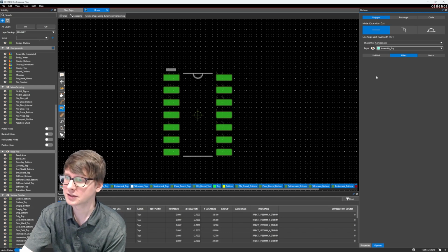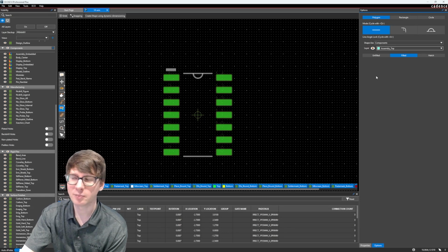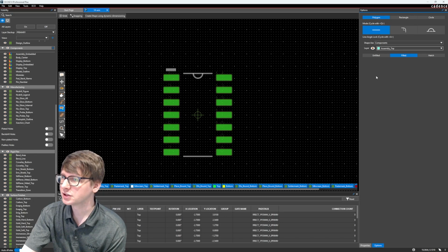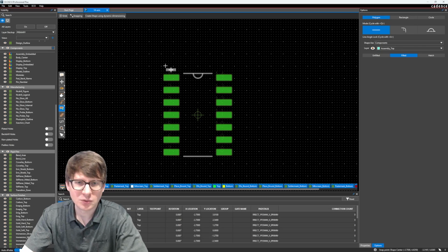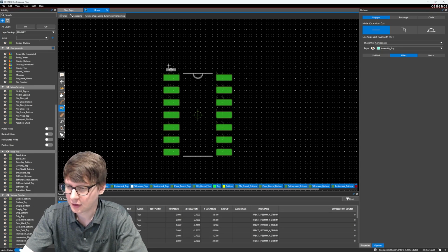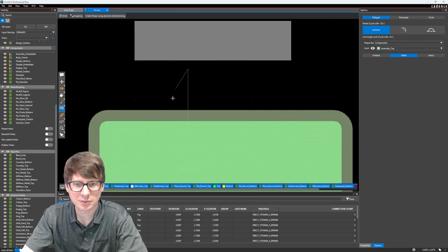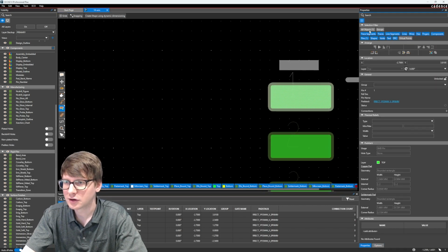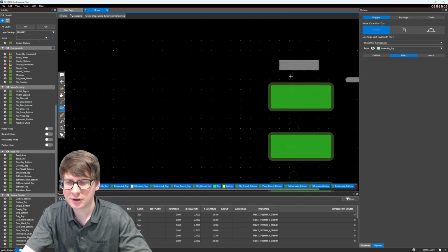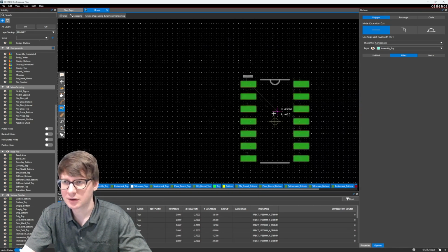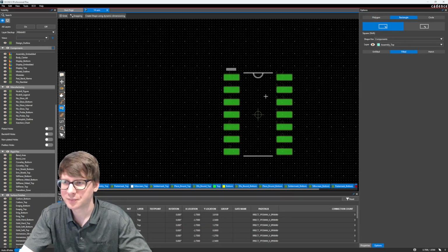For assembly, I like to use the entire outline of a component, including its pins. So looking at the data sheet, it should be 6 millimeters wide by, again, let's use that 8.6. So we'll go out to 3 millimeters in the X direction, which is right here, and should stick to our 4.3 on the height. And let's go ahead and just create our shape right here. Might have to turn off our selection filter. Yep, there we go. So we can start to create a polygon, right? Oh, I'm sorry. Rectangle is what we wanted, but we wanted unfilled.